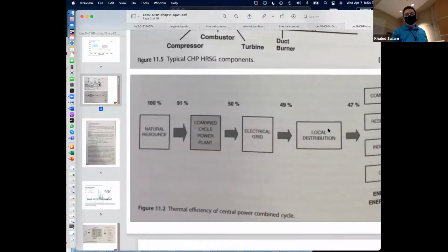Right. So over here he's saying natural gas, you're burning. When you burn, there's efficiency lost in the burning because you don't burn every single thing. And so for our project, when we just think about a gas burner for a swimming pool, don't assume it's 100% efficiency. Check the efficiency of those burners, of those gas-fired water heaters. And you will see it's not 100%, but it's pretty high.